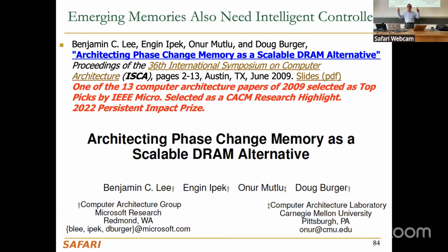Dead is the definition of dead is you cannot read the data reliably from that cell anymore because you wore out the cell. This is also called a wear out problem. It's the endurance wear out, if you hear that. That happens in some memories. DRAM, as far as we know, doesn't have this wear out problem as bad. At least no one has demonstrated that you can wear out a DRAM cell. That's a good challenge for people. If you can demonstrate that, that's actually a very big discovery, in my opinion. But I haven't seen anyone demonstrate that yet.